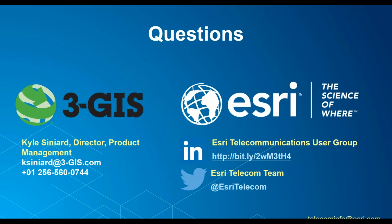Here's a question about fiber representation. How are 144 strand fiber cables represented? One GIS feature or 144? Good question. I think that's kind of where we differentiate from some of the others. We represent that as one GIS object in the database. So one cable with 144 non-spatial tabular fibers that are related to that cable, which allow you to drill down and capture as much or as little information as you'd like against each fiber inside your network. But it is just one line on the map.